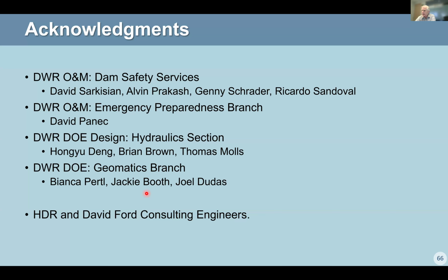For instance, for Oroville, folks love to talk about the breach parameters, just like they like to talk about Manning's n and such. We do a sensitivity analysis for Oroville, and we show that it really doesn't make a difference between 1 hour and 4 hours, at least at the level of these maps that we're interested in here. That's the best thing we can do for these types of applications.